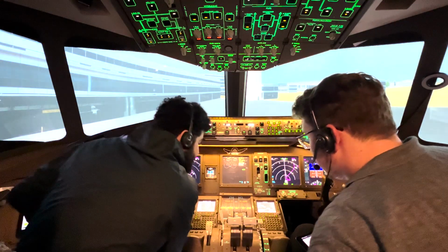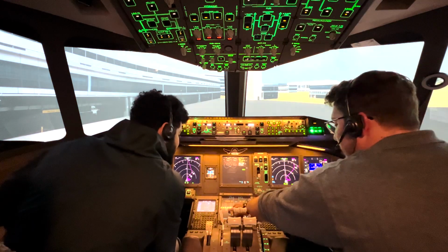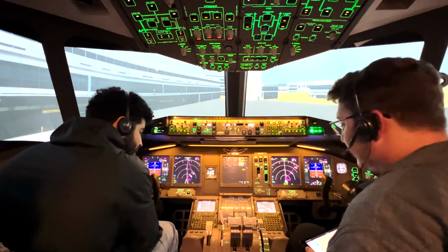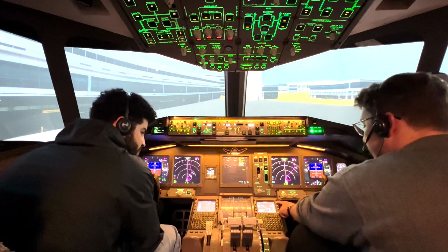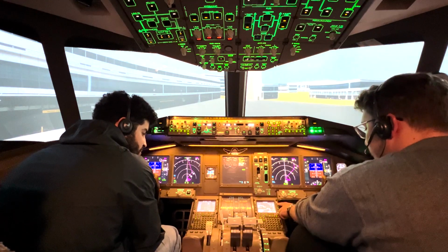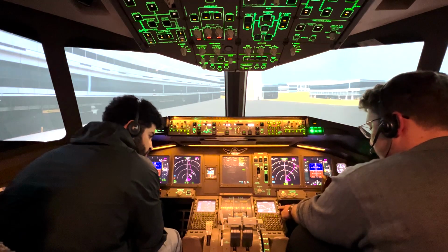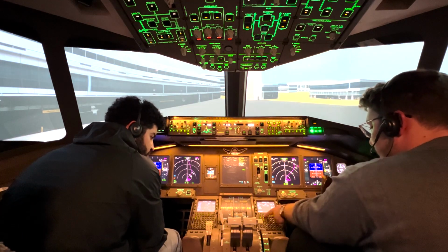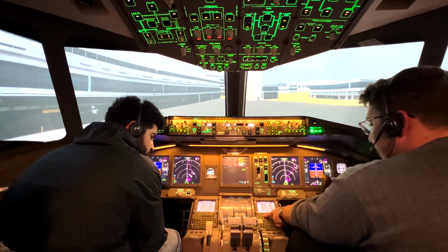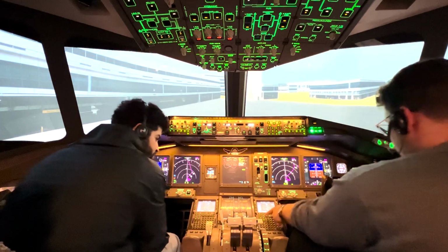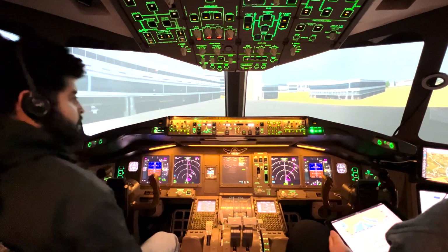And where do you see that? Right here. Stabilizer trim. Okay, I see, yeah. So we have 5.73, that's good enough. Our V1 speed is 131, rotate speed is 138, V2 speed is 148, thrust limit is set, and we'll keep this page on the legs page, and we're ready to start off with our checklists.